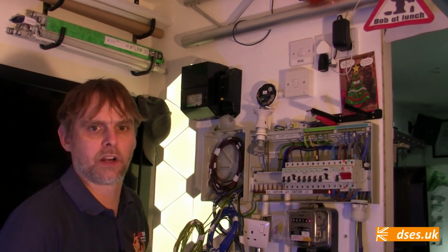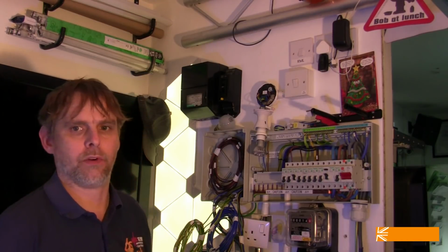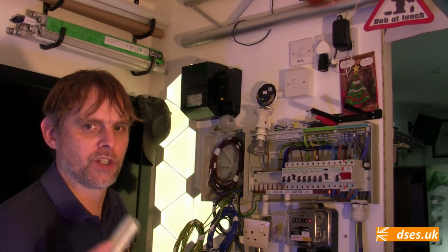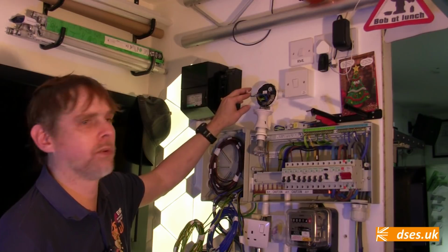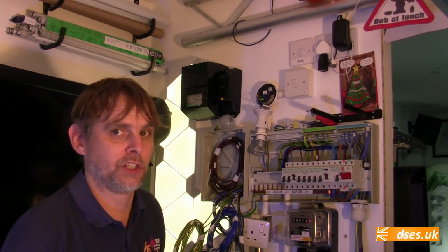So there we go, that's the way to fix it if the problem is capacitive. Cheap to buy, easy to hide, lasts for years and costs nothing to run. If capacitive induction is your problem, then consider it solved. Just make sure the neon indicator you source is suited to the voltage in your territory. Let's move on to problem number 2, which is smart switches.